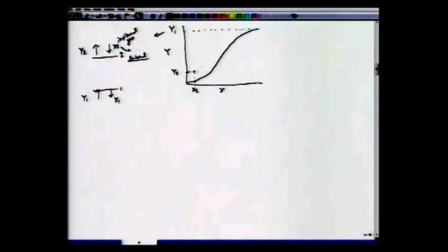Now what we have to do is find out, if you have a general operating curve, then we will have the operating line something like this with the slope Ls by Gs. Now in this case, when the shape of the curve is S shape, we have to be careful in the sense that from here we have to draw a tangent like this to this curve.